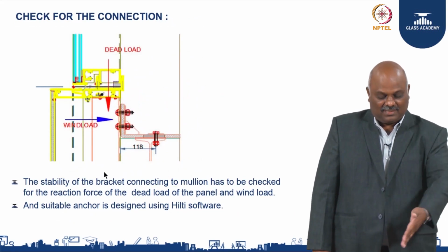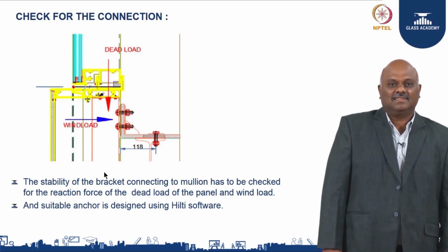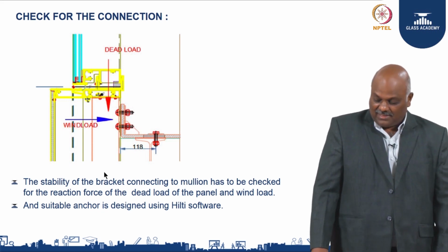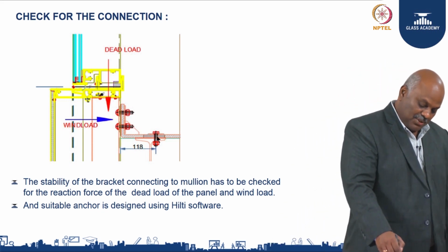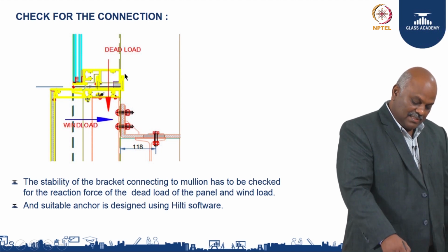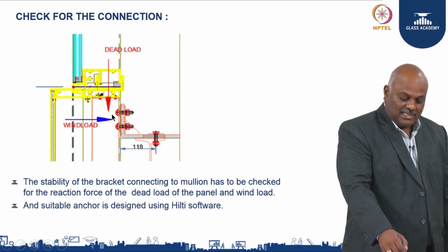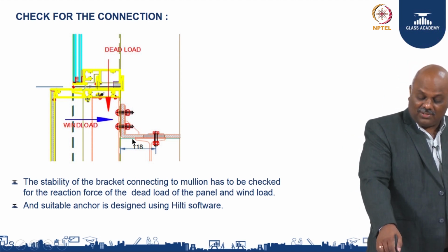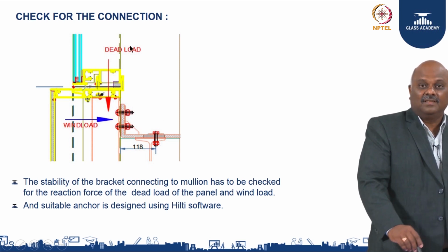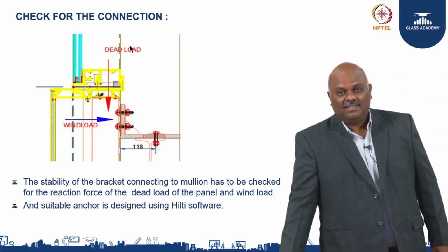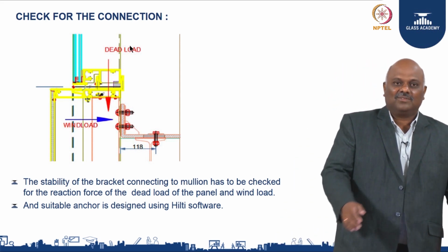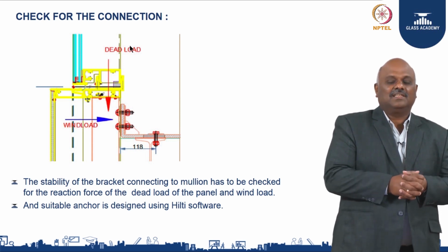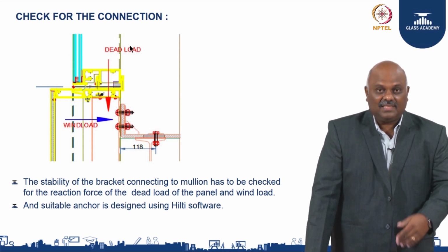Once you pass through, then you design your bracket system and anchors. So what bolt sizes you need and what loads they are going to take care of. The bracket system you have should restrain the wind load as well as the dead load. For example, these two bolts here act in shear, but at the same time this bracket here, this bolt will go into shear as well as uplift. So you have to design for combined forces. Sometimes you will see both tension and compression. Those sort of things have to be studied properly before even engaging on design.